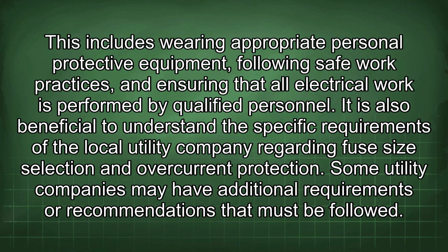This includes wearing appropriate personal protective equipment, following safe work practices, and ensuring that all electrical work is performed by qualified personnel. It is also beneficial to understand the specific requirements of the local utility company regarding fuse size selection and overcurrent protection. Some utility companies may have additional requirements or recommendations that must be followed.